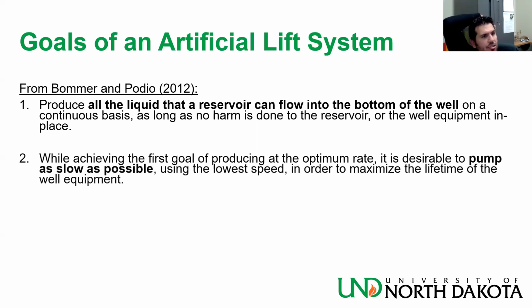And second, while achieving the first goal of producing at the optimum rate, it is desirable to pump as low as possible, using the lowest speed in order to maximize the lifetime of the well equipment. And I want to stress this second point because you don't hear that a lot outside. You go to a conference, they show you artificial lift hardware, and they tell you about having the maximum possible rate. They are going to talk about maximizing the flow rate. And this is not the only thing that you should care about in the well.